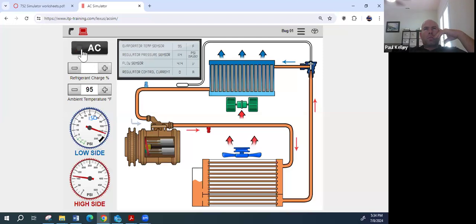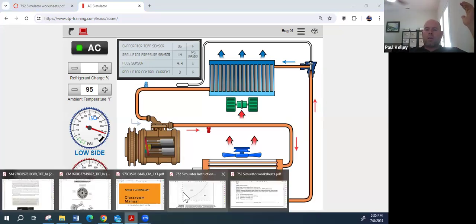But does anybody notice something here? What's happening here? The green AC light is flashing. That's interesting. Do you guys learn about that in the reading a little bit on the Toyota manual? A code would be on a new system, yes, but on an older system before they set DTCs, this was more of an indication of a fault. This is saying there's a problem in the circuit with the AC compressor clutch. We don't know exactly where in the circuit, and unfortunately can't do voltage readings. So we've done as much diagnosis as we can.